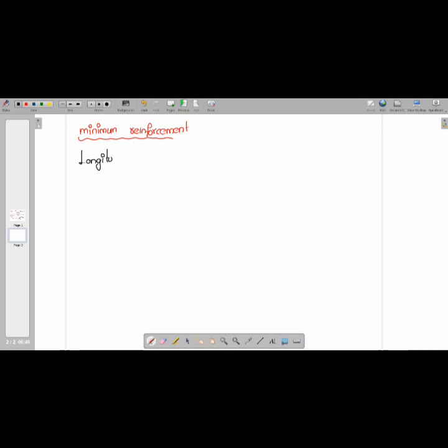It is 0.2 percent of gross area for mild steel, and 0.15 percent of gross area for HYSD bar.